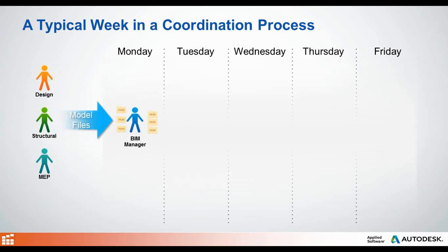I ask almost every team I work with, when do we think that clash report is out of date? My answer to that is the clash report is out of date the moment it's printed. Because the moment it's printed and sent around to our various disciplines, here design and MEP, they're basing their changes off of that printout, off of that PDF. They're not basing their changes off of one another's latest version of their model.